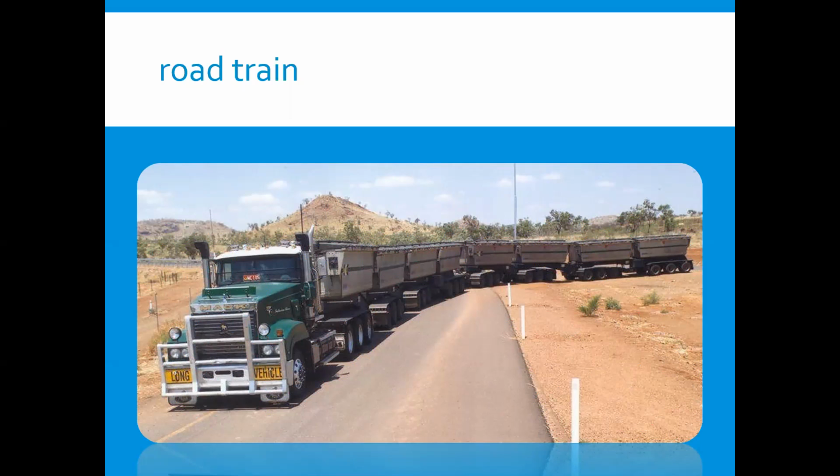Larger vehicles, let's say 33 meters B-triples and 30 meters Super B-doubles, and those operating under the restricted access conditions may also be catered for, but this will usually involve encroaching into the other traffic lanes. This may cause some inconvenience to other road users, but may be acceptable because of the low frequency of occurrence, together with the fact of special conditions associated with the permit.